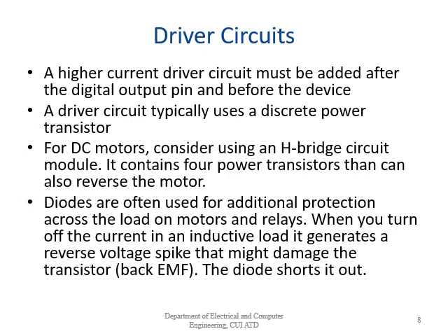Now, what does a driver circuit mean? A higher current driver circuit must be added after the digital output pin and before the device. So we need to have a driver circuit before the device which we are driving, or after the output from where we are generating the digital output. A driver circuit typically uses a discrete power transistor. So whenever you look at driver circuits, they will comprise a power transistor. For DC motors, consider using an H-bridge circuit module.